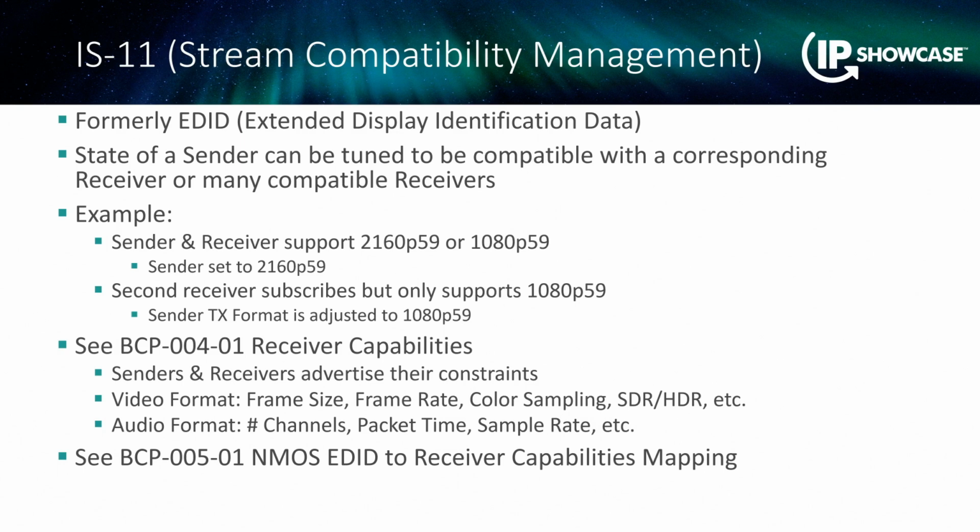It's extending into HDMI type realms, Pro AV. So things you might want to know are things that you get on HDMI, this thing called EDID. It says, what are the capabilities of my display? What are the capabilities of my receiver? How can I make sure I'm not sending an incompatible stream between A and B?